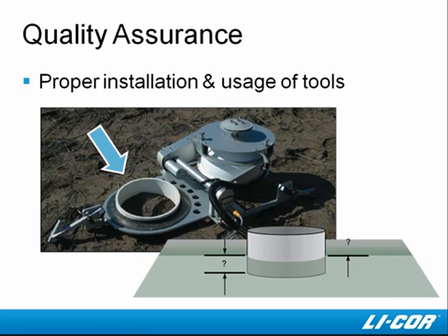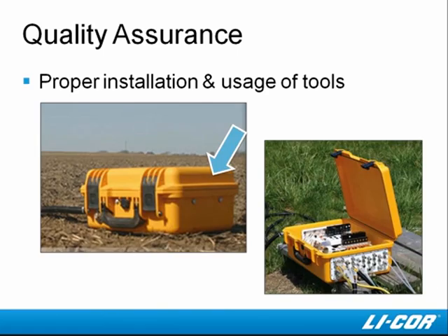Our manuals give detailed information on installation and usage of the LI-8100. For example, it is important that the soil collar provide a mechanically stable measurement interface between the chamber and the soil. Soil collars are covered in Chapter 2 of the manual. Although weather-tight, the instrument connectors and cases were not designed for submersion. In long-term, unattended measurements at sites which may be exposed to intense precipitation, it is important to keep the instruments up off the soil using bricks, blocks, or even a pallet, as in this example.